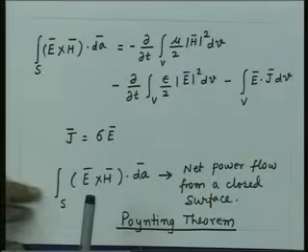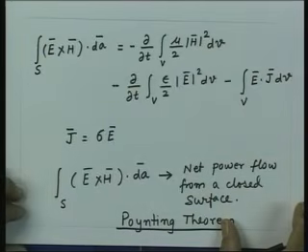In fact, there may be some very special pathological cases where this argument will fail, where E cross H at some particular point may give you a power flow whereas actually there is no power flow. So, while using this quantity as the power density, one has to be a little careful. However, in most practical situations, as I mentioned, this arbitrary definition that E cross H gives me the power flow density at a particular location normally is valid.